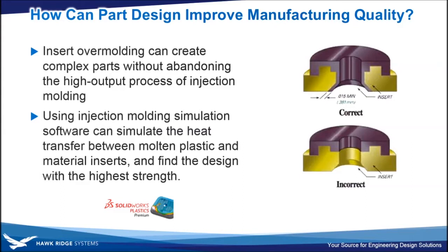And so injection molding software, in general, of course, can simulate what the filling and packing and cooling phase of that cycle looks like, and tell you roughly what the quality of the part will be, and if there are changes you could make to the material or to the gate location, to get a more easily manufactured part and higher quality part.